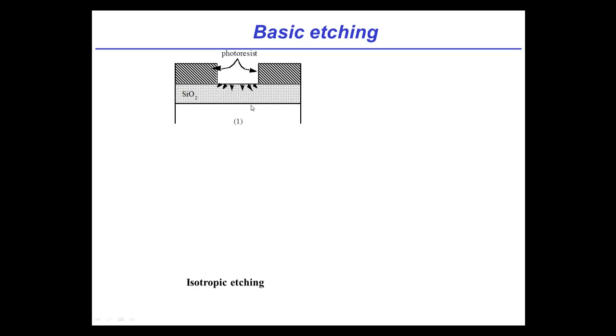So let's say I've got a silicon wafer, and I've somehow got a layer of silicon dioxide on the surface. Now, we haven't told you how you put silicon dioxide on the surface. We will in a minute. There's a couple of different methods. But silicon dioxide is what happens when bare silicon interacts with oxygen, and it's basically glass. It's silica glass, and so you get SiO2. Okay, so there'll be a thin layer of this glass on the surface.